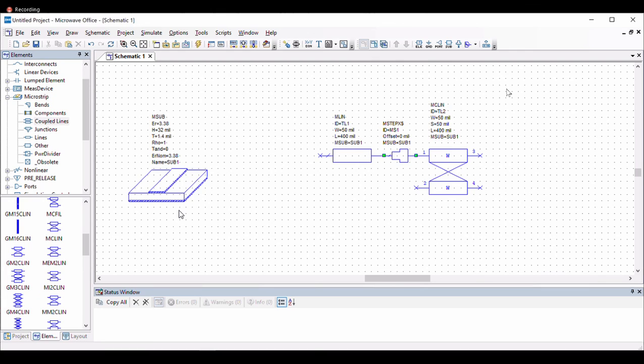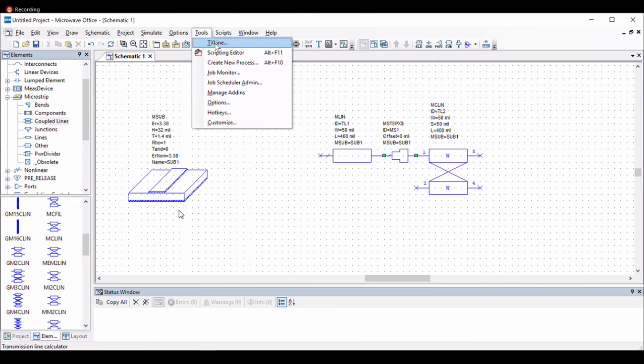Okay. So the other question is, I can change the width, and I get the physical design, right? But when I do the circuit model, it tells me 100 ohms, 70.7 ohms. How do I translate that? There are a lot of calculators online, but here you have a tool. If you go to the top menu of AWR, there's a toolbox. The first one is transmission line, TX line.